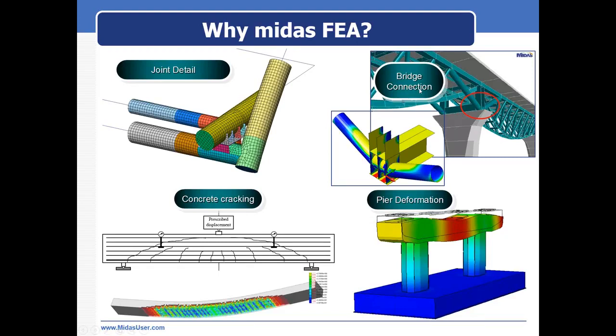Next is bridge connection. Generally, what happens is, these steel trusses are rested upon this pier cap. At this location, there is high stress concentration, and these stresses cannot be obtained using frame modeling. So to get these stresses and to check whether the stress satisfies the limit or not, we have to go for finite element modeling. And there, FEA comes to mind.